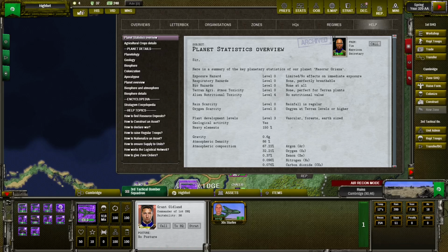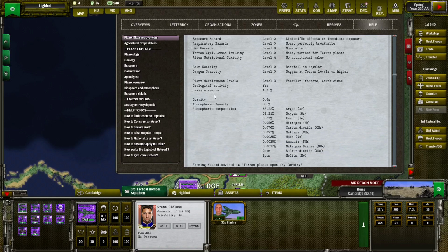But if we go back and scroll a little here, there is information about planetary gravity and atmospheric density, which are also crucial for our design. Especially the atmospheric density impacts the effectiveness of the wingspan, so how big a lift we can get from the surface of the wings, and the gravity, so how much the weight of everything that we are adding will impact our engine power.